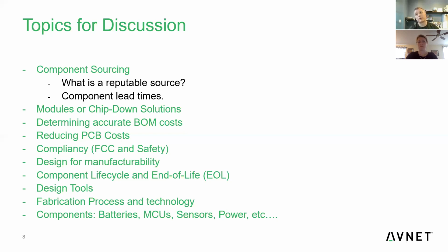There's a couple products we've come across that might be a little bit higher, but I've yet to see a product come through the Hardware Studio Connection product that uses direct AC. So being a low voltage product on an adapter, or a wall wart, as we tend to call it in industry, basically saves you from having to do the safety compliancy.